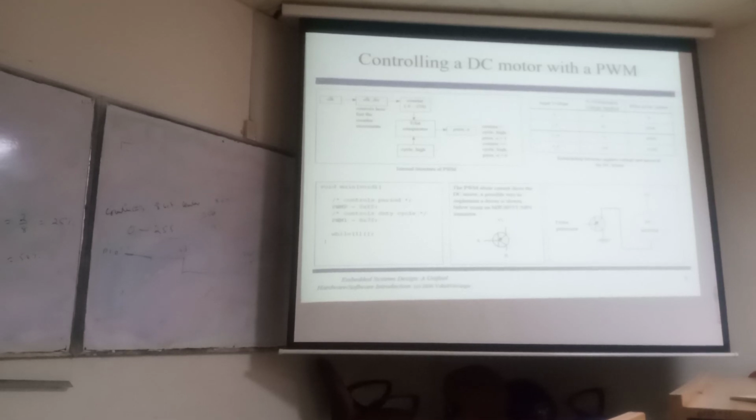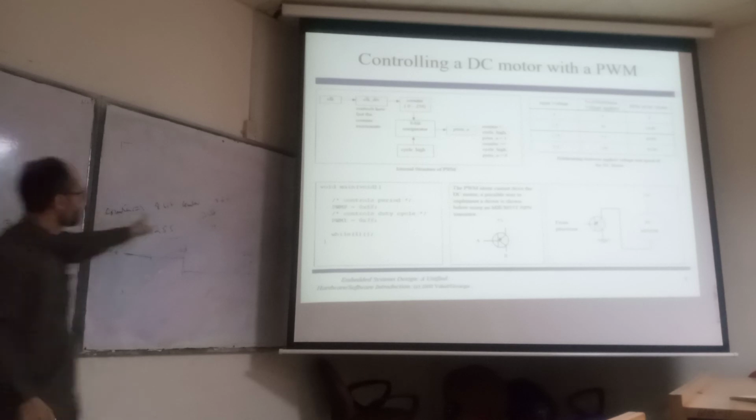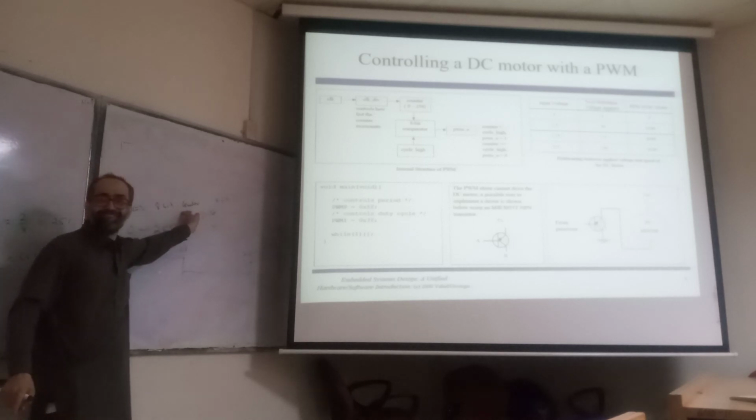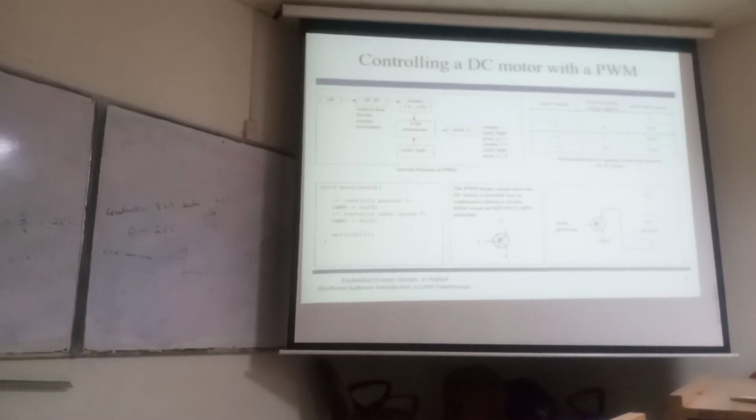Let's assume we have set this signal; initially it's 1. Set P1.0, decrement R0, compare R0 with 64. We are generating what? Duty cycle. Yes, 25%.